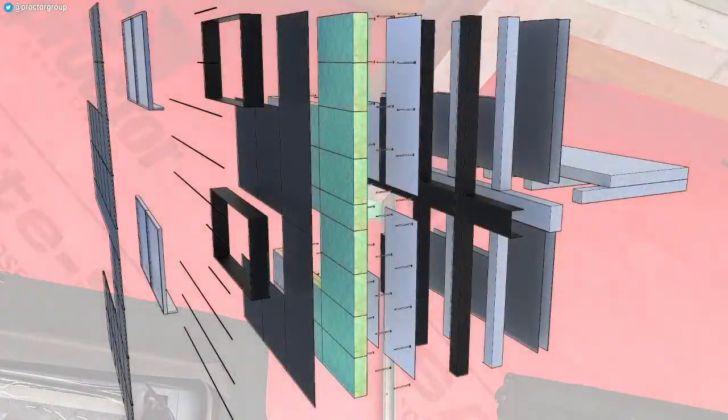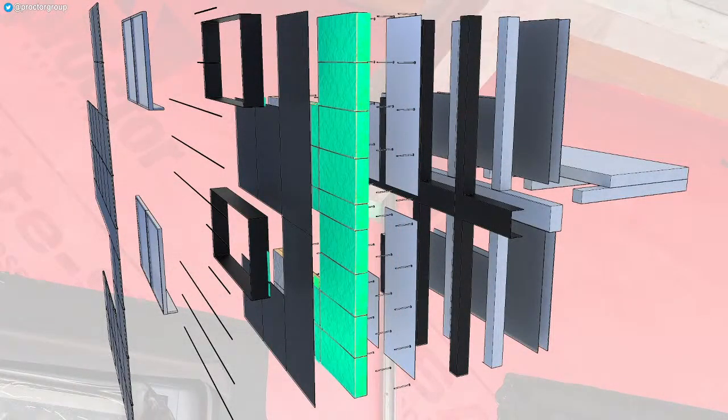As well as the obvious reduction in building footprint from the reduced insulation thickness, there were several additional benefits. A detailed WUFI condensation risk analysis on the use of Raptite allowed the removal of the internal vapour control layer and its associated installation costs. The use of Raptite also allowed a reduction in the specification of the sheathing boards, owing to the weather tightness of the membrane externally, and reduced the requirement for EPDM membrane over the structural frame, infills and at flashings around windows. Taken together, the cost savings from these changes more than offset the increase in membrane costs from the use of Raptite, allowing the specific project goals of improved fire performance to be delivered alongside a cost saving.